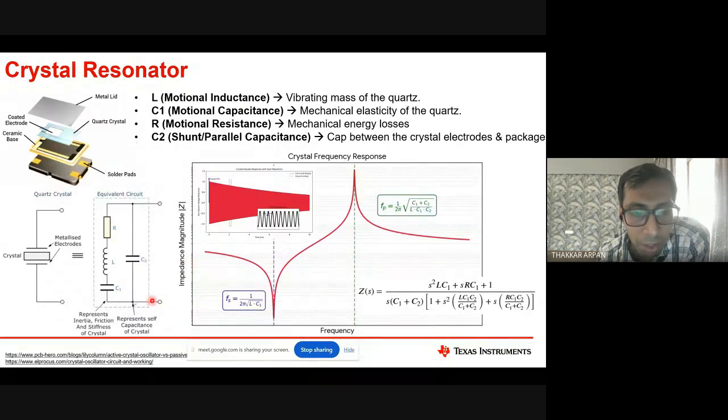Okay, and that square wave will be supplied to this crystal network. And crystal network is a very sharp filter, right? So it will filter out the square wave's additional harmonic components, and it will just generate the sine wave. Once it generates that sine wave, as it is a cross couple pair, depending on the amplitude, it's a positive gain system, right? So whatever it gets, it will again increase the amplitude. But it will settle at some point, right? Whenever the loop signal gain becomes 1, at that time only it will be stable.